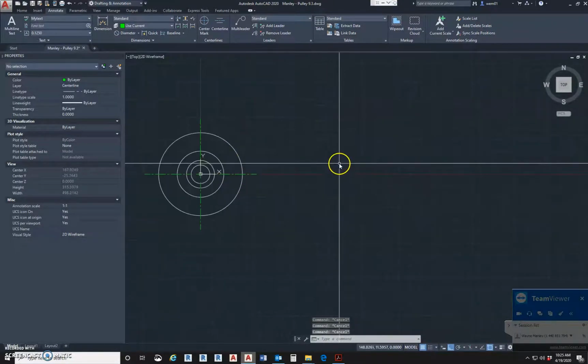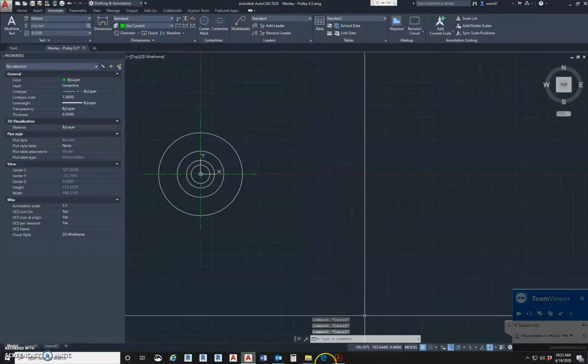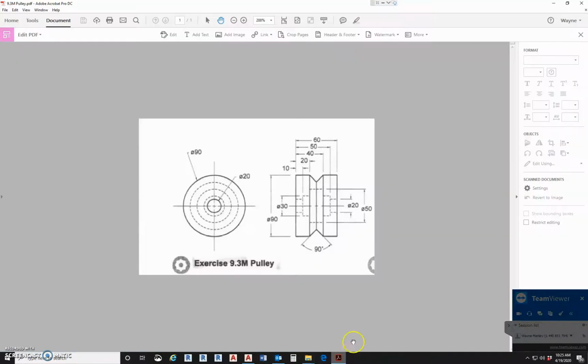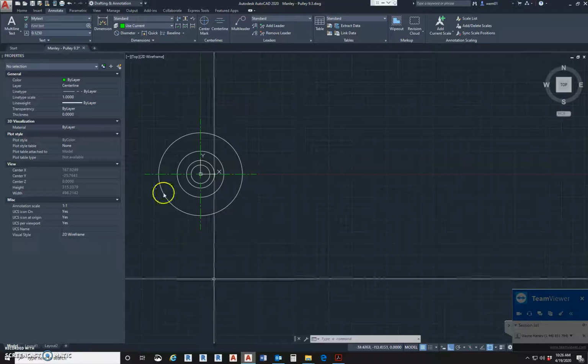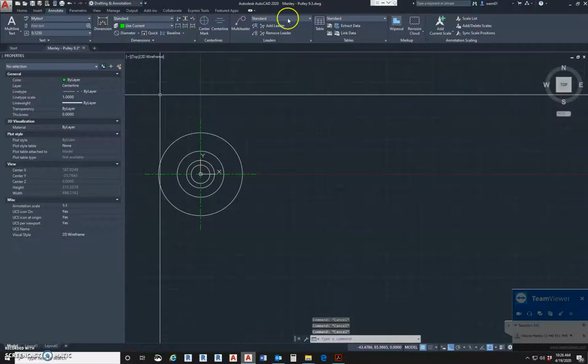So now we're going to draw this elevation here. And what we know about the elevation is obviously we can project things over. And they're giving us dimensions going across here, okay? But what I want to do is draw the solid lines. The hidden lines are going to come back and get a little later. Okay? So in order to do that, one thing we got to do is get our projection lines.